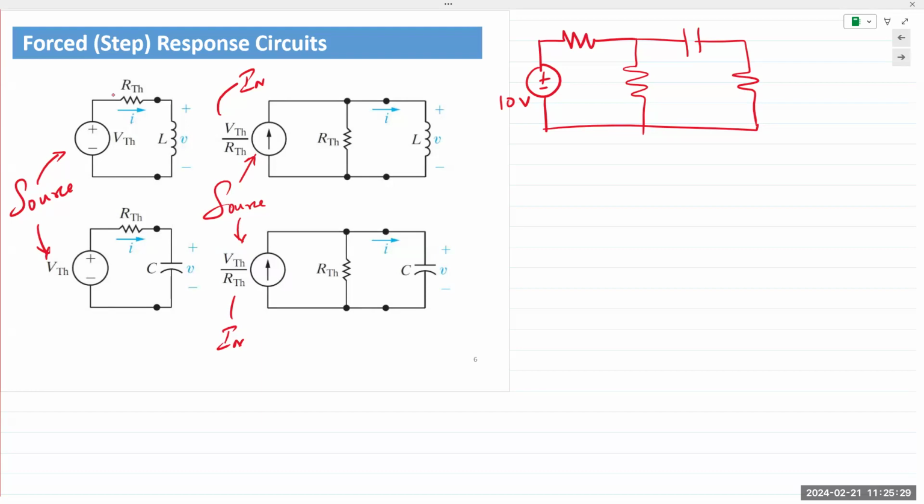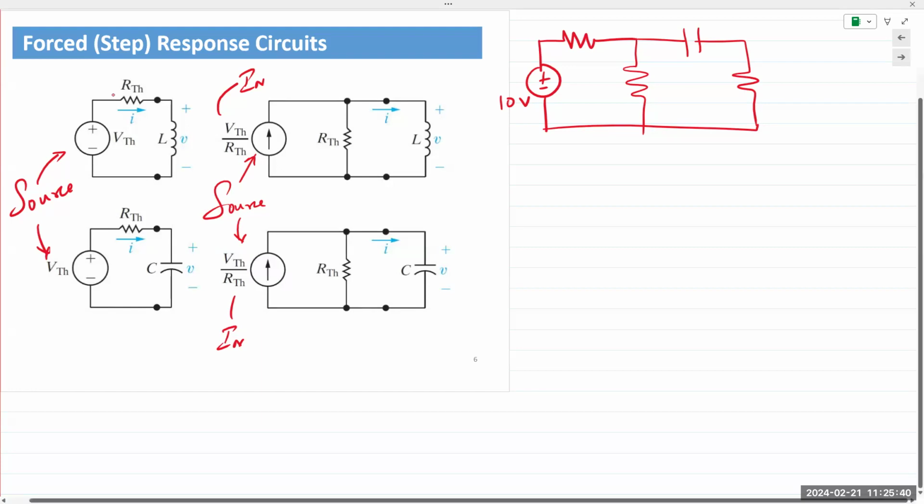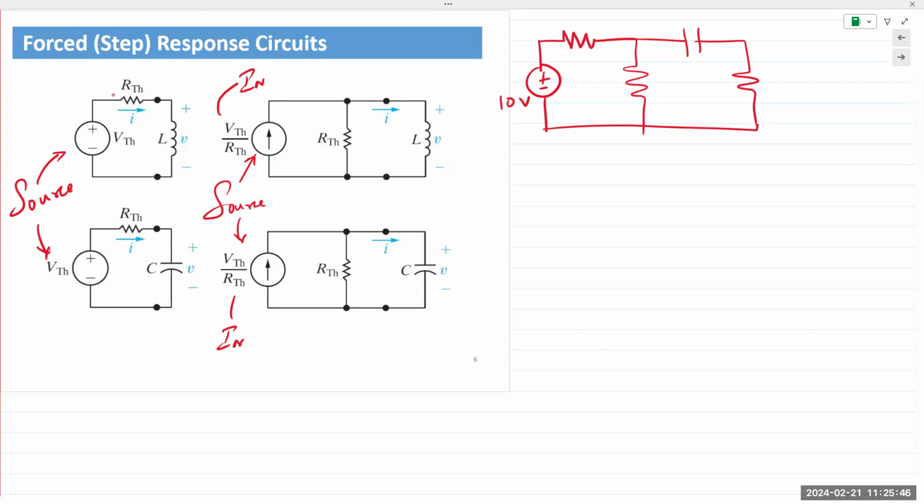If you apply 10 volts, do we expect 10 volts across the capacitor? No, because the voltage or the current that's being supplied by the source will be dropped across all 3 resistors. Not the last one so much, just because, well, actually, no, even the last one is included, because the current actually charges through that resistor. So all 3 resistors are involved in the charging and the discharging phase.